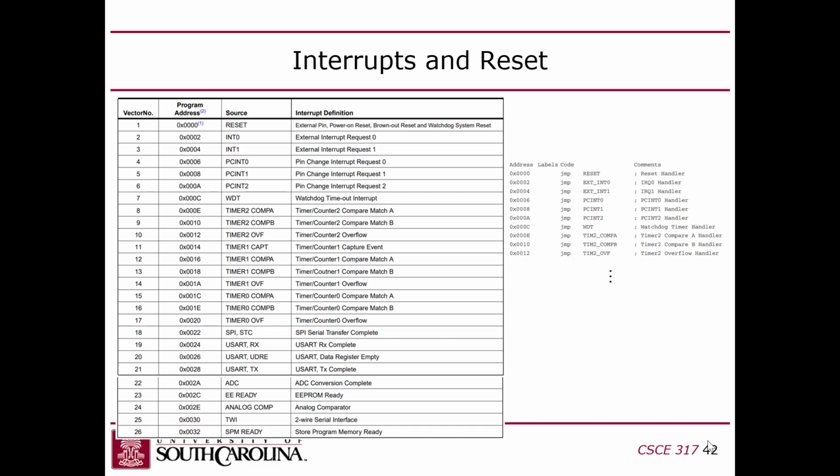What kind of events? Well, there's two external interrupt pins called int0 and int1. Those are just pins on the board that you can plug one bit into. Their inputs. So you plug a wire into them that is driven by an external device that's using the same voltage. And so you can trigger an interrupt when the bit on that pin goes high or goes low. You can make it rising edge or falling edge active, or you can trigger whenever the value goes high or low, or is high or low. Those are external interrupts. But then there's internal interrupts.